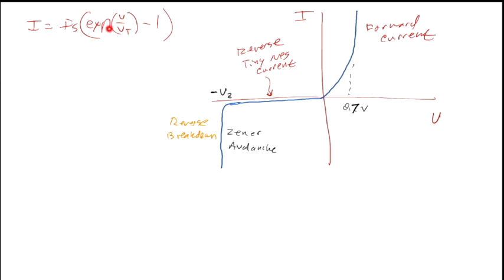And you've got a large number multiplied by a small number. It becomes a bigger number, and it's exponential, and that's quick to happen, because VT is about 0.0258. As this gets particularly large, above say 1/4 of a volt, then this number becomes a real current that you can measure as microamps and milliamps easily, even amps.